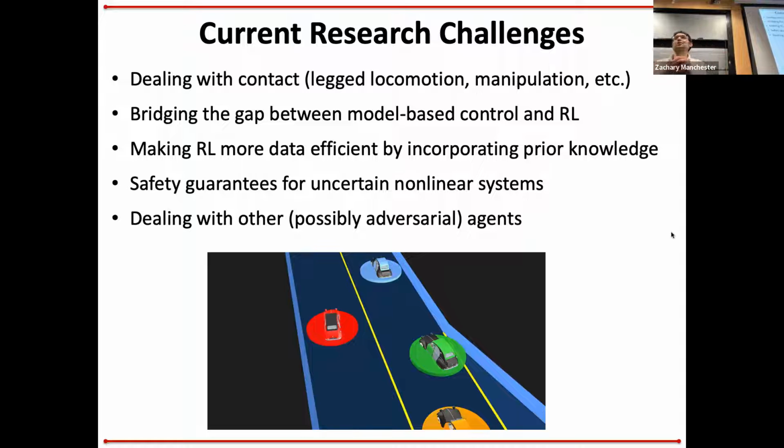You end up with discontinuities in the dynamics, right? So you end up with giant, spiky things that happen in your contact forces when your foot hits the ground and stuff like this. And you get non-smooth dynamics, which means you can no longer take nice gradients through things and do standard gradient-based optimization, which makes these problems super, super hard.